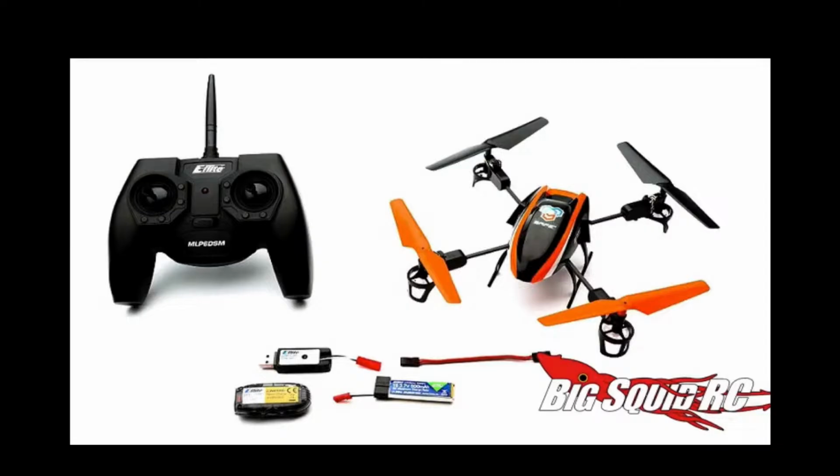And so it knows what flat is, essentially. When you turn it on, it says, okay, this is flat. Then when you fly it, if you give it some input to the right and then you let go, it's going to go back to flat. Whereas an unstabilized one, if you put it to the right, it would just keep going to the right until you correct it. Until you correct it with other input, yeah. These have the basic style, which will level itself, but it doesn't know its GPS location. It doesn't know how high up off the ground it is. So it's sophisticated in that it can help stabilize your flight.